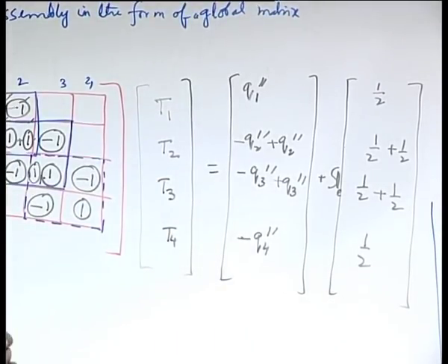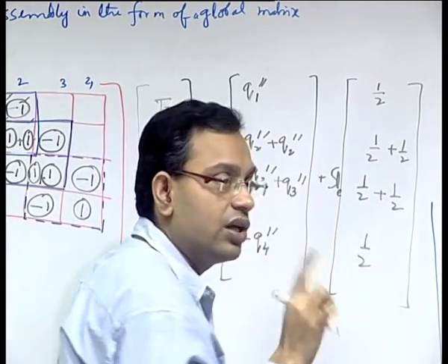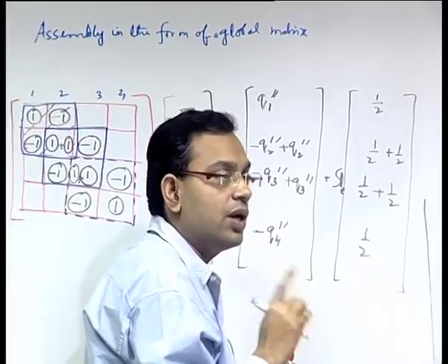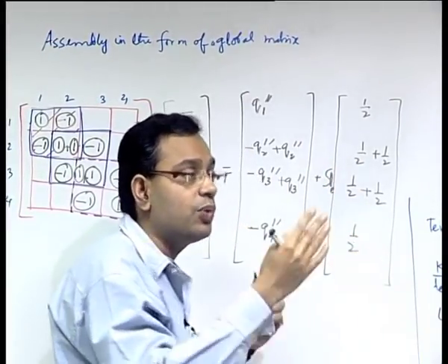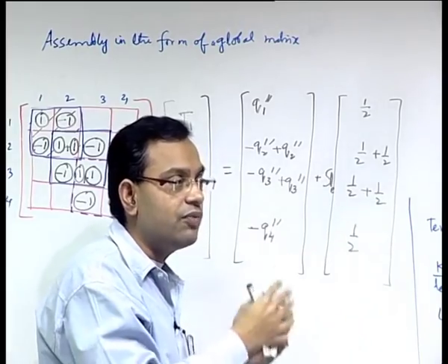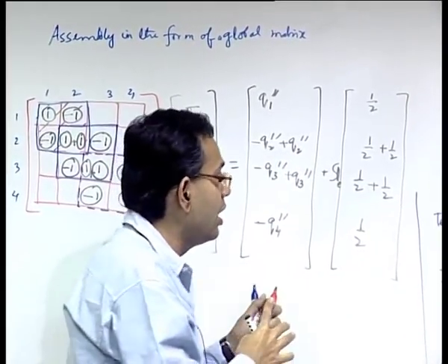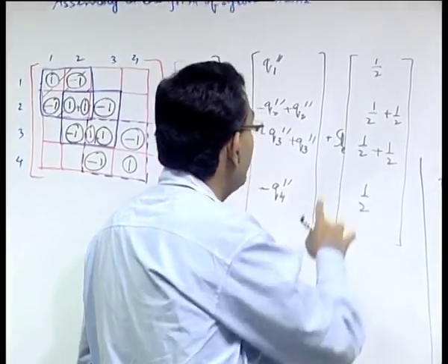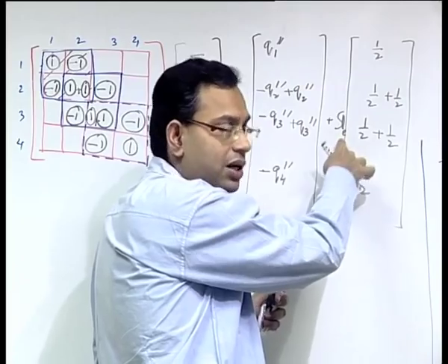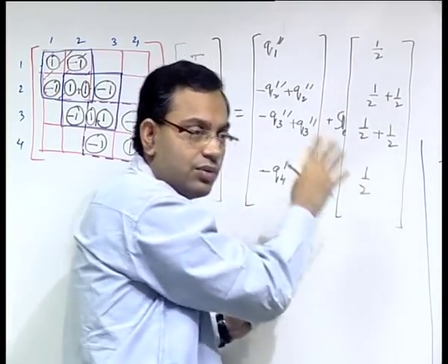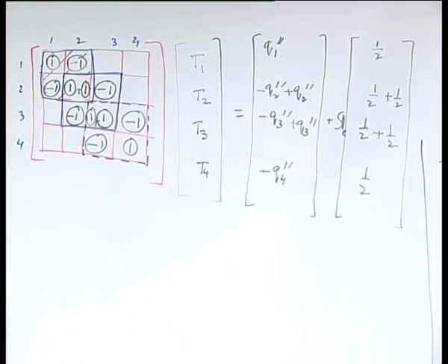What is an important assumption that we have made? We have made an important assumption that K is a constant, that is the thermal conductivity does not vary from one element to the other. But if it is a composite material, then it is possible that different elements have different thermal conductivities, that is what we have not considered. And the other simplification is that we have considered each element to be of same length, that is not necessary, but just for algebraic simplification we have put it, otherwise different elements will have different length.